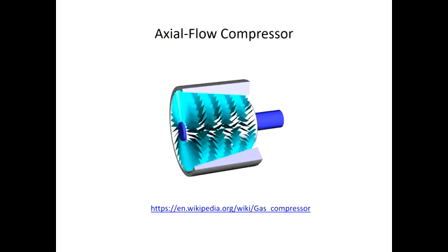And the compressor can certainly come in different designs. This is just one type. You can use a piston compressor, which is similar to a car engine, but the purpose is not to output shaft work, but just to compress the gas to produce a high pressure gas as the output, right? So that's the compressor. Maybe there are a few more examples. Maybe I'll discuss all of them first, then show the slides to avoid switching back and forth.